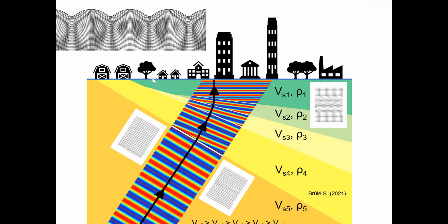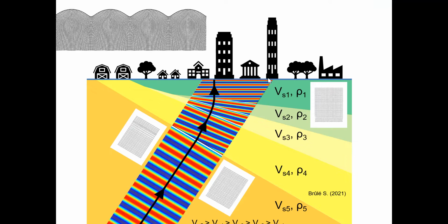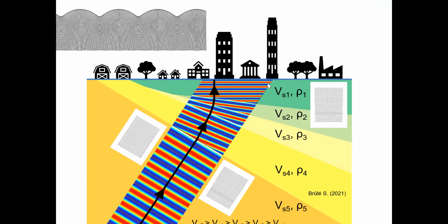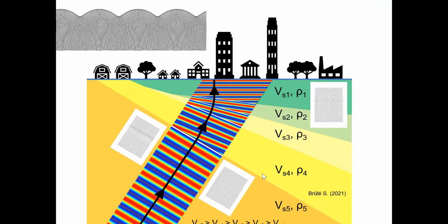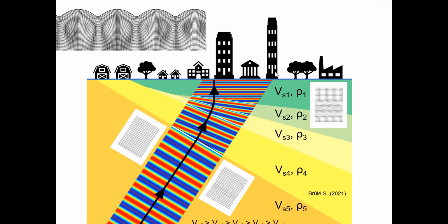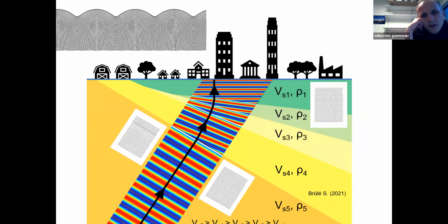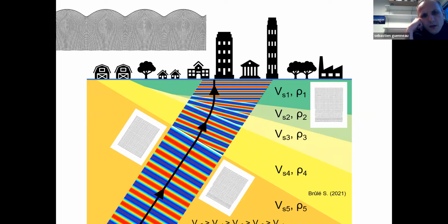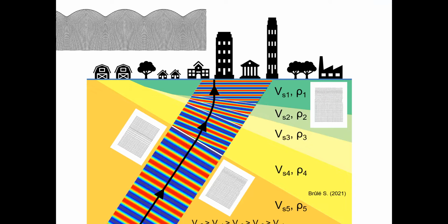Okay. So this huge building is not in a good position, because the soil here is thick and maybe the soil is soft too. So it could have the same fundamental frequency as the soil. Okay. If the basin is thick, you don't have a tall building.